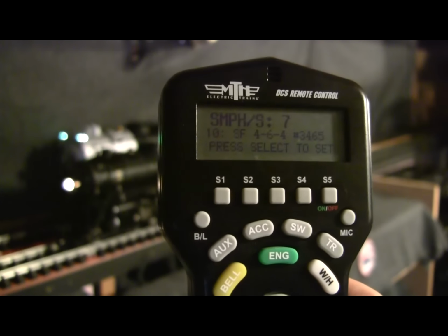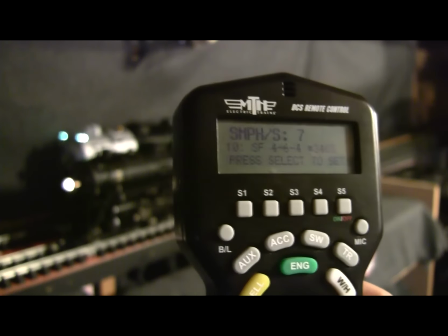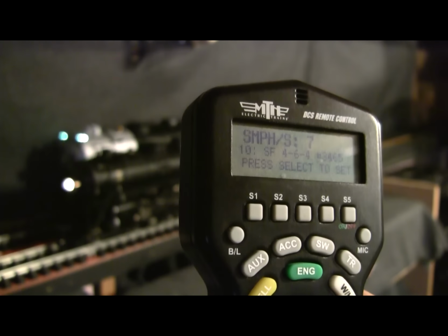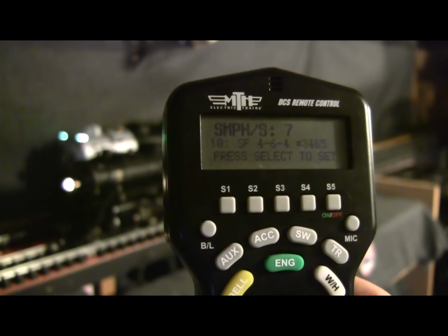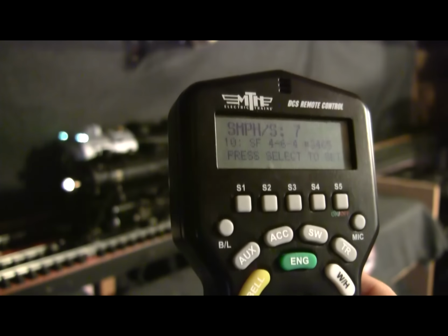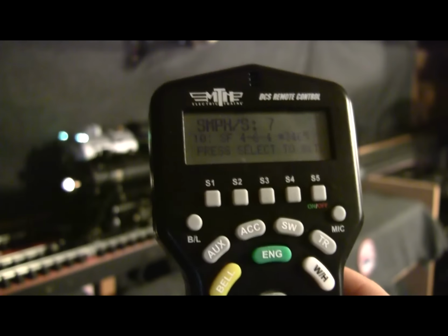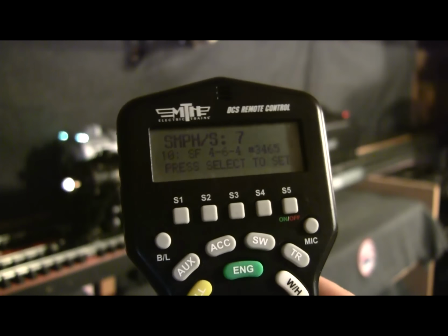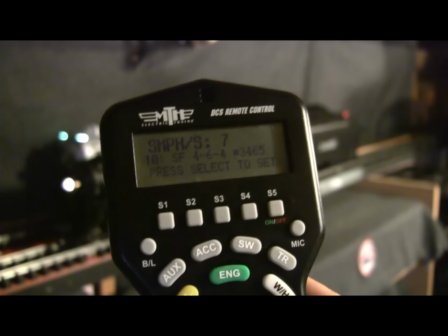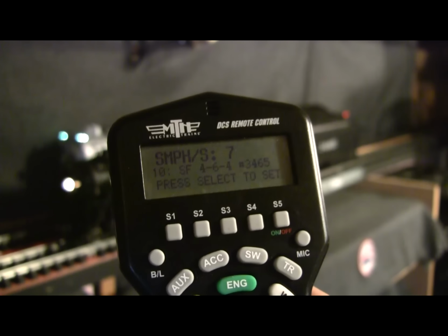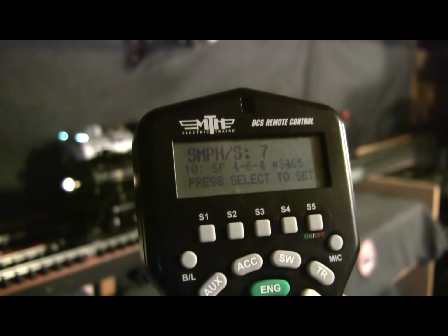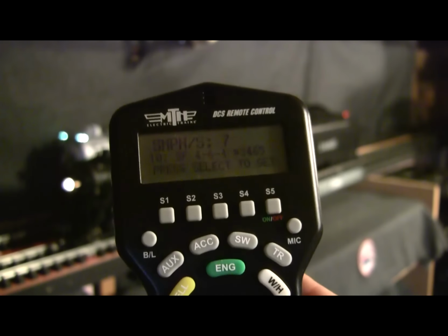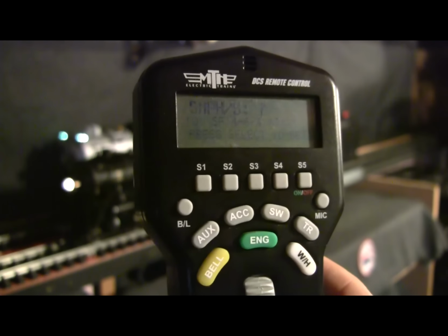Deceleration rate, basically the same thing. This allows you to have either a quicker deceleration, or a slower deceleration, depending if you need to stop the engine quickly. If you hit the direction button, if you have the deceleration rate set too low, while it is probably more prototypical, if you have a derailment or something, you need to stop the engine fast. It could be an issue if you have it set too low. So.